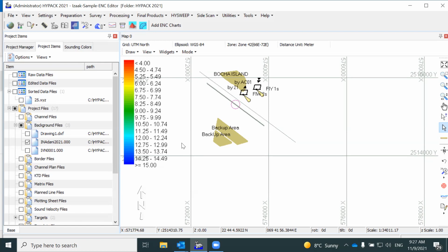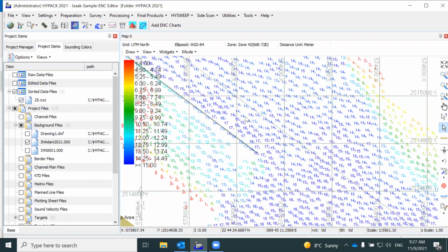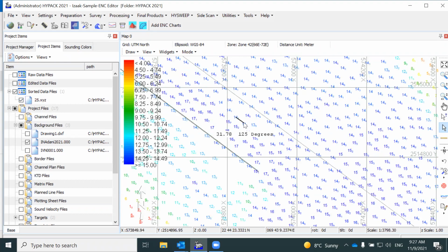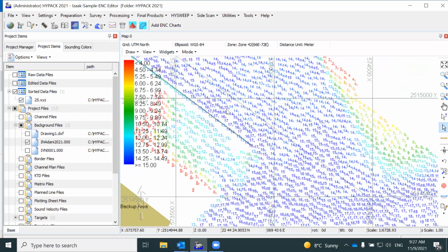When you incorporate your soundings into S57 chart, you still may keep in mind that you need to reduce your soundings. Let's have a look at the soundings which you have provided to me. And let's see, they have like 30 meters between the soundings, right? Our chart is 10,000 scale, right? It's 10,000 scale chart. So it means that we have 100 meters in 1 centimeter.